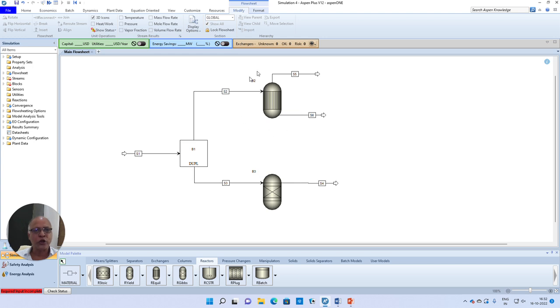That's how it tries to calculate based on this particular equation. Whereas the Gibbs reactor model will try to minimize the total Gibbs free energy in order to calculate both phase equilibrium as well as reaction equilibrium. Try to identify the kind of inputs that you have to specify for both these reactor models as we progress.